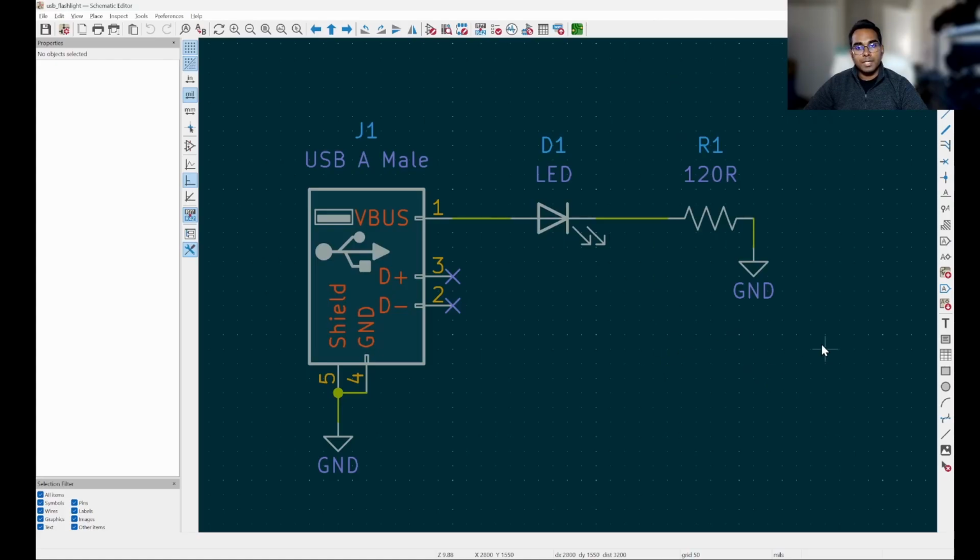Now, the very first of these is the ability to import third-party footprints and symbols for new components. Say we wanted to use an LED or a resistor that was an atypical format. It's a different footprint or size that's not commonly used, and KiCad therefore doesn't include it in its libraries by default. Well, then we'd have to go to the manufacturer and see if they give us some 3D models, some footprints, or some symbol files that we can import into KiCad and use in our design.